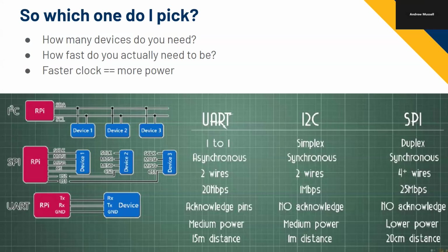When you do the STM32 Cube IDE, you assign the pins before you start working on your code. So you would assign these pins to be a SPI bus and these pins to be an I2C bus. And there's only certain pins that have functionalities for certain buses. So when you're an electrical engineer, you need to make sure you connected the correct I2C pins to your I2C device and you have the correct pull-ups. And then you work with the CS engineer and it's like, okay, these are the pins we need to set up. Here's the speed the bus is going to communicate at.